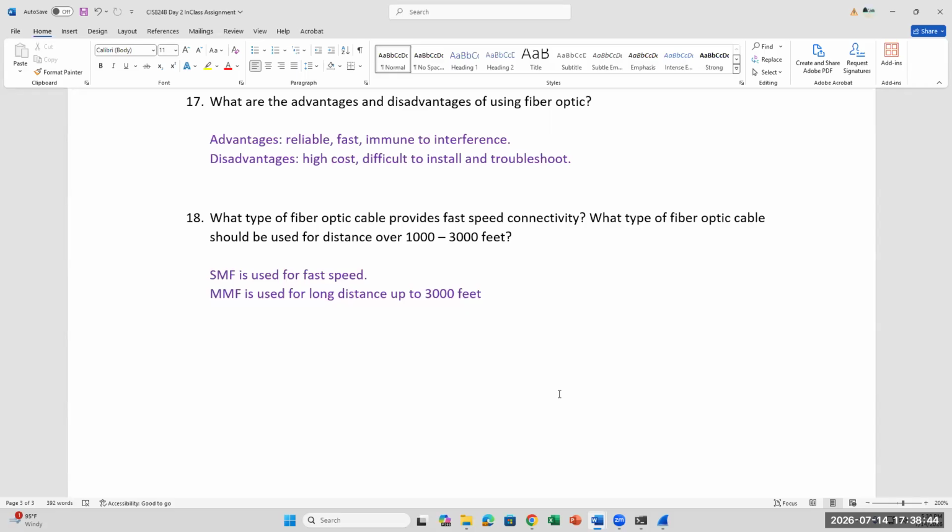So I thought between buildings would be the single mode. Yeah, single mode is between buildings. You can use multi-mode across the buildings too, I guess, but it will be more efficient if you use single mode. But if you have access to multi-mode for everything, then multi-mode it is.